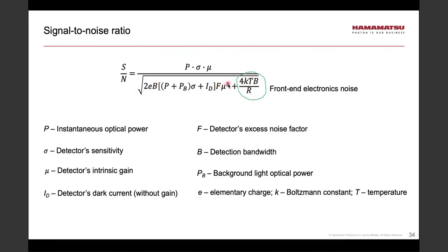Just before we close this presentation, just a few comments. The excess noise factor for a typical PMT and SiPM is comparable, and it's about 1.1, 1.2. However, in the case of an APD, the excess noise factor, F, can be as large as 3, 3.5, and maybe even 4. So some photodetectors have, as I like to say, quiet gain, but others can have actually quite noisy gain.